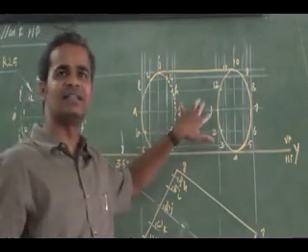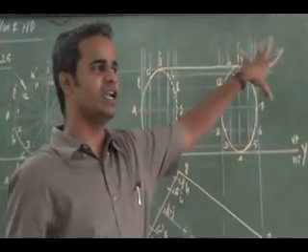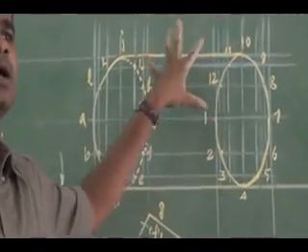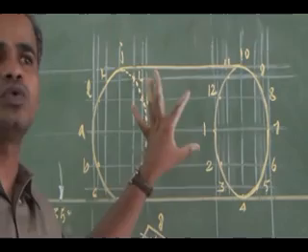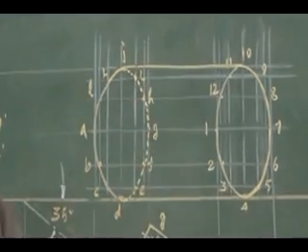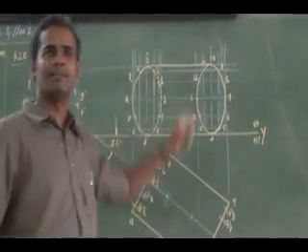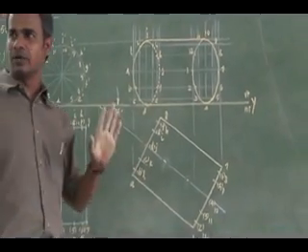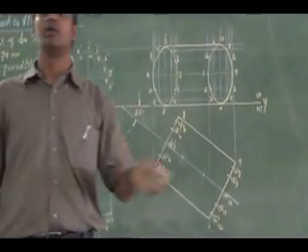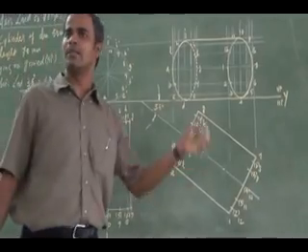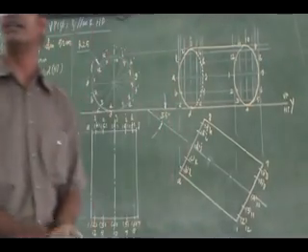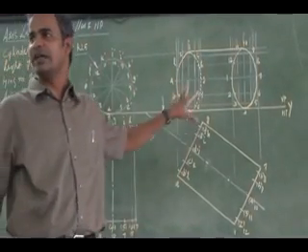In this front view, the extreme generator of the cylinder will be shown as a dark one. That is nothing but the boundary of the cylinder, shown as continuous. The inner generator should not be shown as visible. The projector lines will be shown in light pencil. As far as cylinder and cone are concerned, only the extreme generator will be shown in your view. To get the base points, we mark and extend the projectors. Is it clear? Do you have any clarification in this?